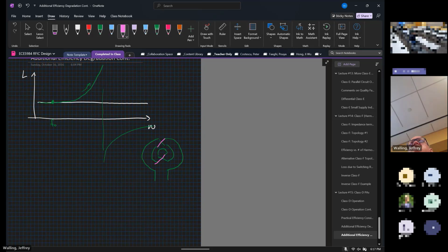Well, normally I'm going to be passing a DC bias through that. If I'm moving to a lower metal, it's going to have a much larger series resistance, so I'm going to have a larger IR drop on that. Except IR drop, is there any specific reason? I also am going to get myself closer to the substrate for not necessarily any good reason. I want to avoid being near the substrate if at all possible. What you typically want to do in an RFIC is make my devices and then route away from the substrate, getting to less lossy metal as fast as possible.